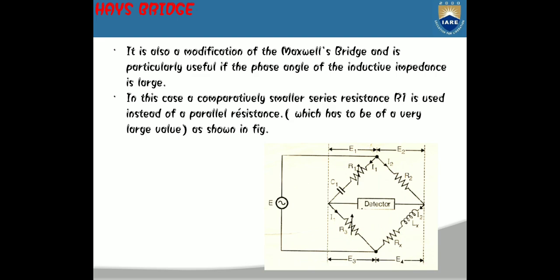The frequency dependence of inductance values gives rise to other constraints on this type of bridge. The calibration frequency must be well below the lesser of the self-resonance frequency of the inductor and the self-resonance frequency of the capacitor. Fr is less than the minimum of the inductor and capacitor self-resonance frequencies divided by 10.